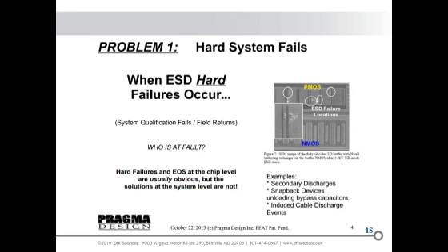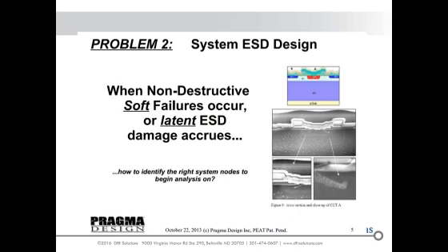So the next issue on the failure analysis on the next slide is actually from an NXP research paper that showed a common problem, that filaments are grown within junctions and devices such as ESD clamps, where there is nonlinear concentration of current flows in a junction or in the substrate that create these micro annealing, or these little filaments that grow, and they will not demonstrate any visible or electrical failure signatures until they grow far enough to puncture the junction.